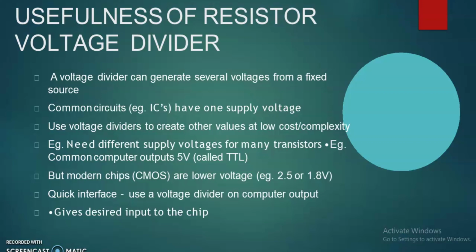Where frequency response over a wide range is required, such as in an oscilloscope, a voltage divider may have a capacitive element added to compensate for the load capacitance. In electric power transmission, a capacitive voltage divider is used for measurement of the high voltage.